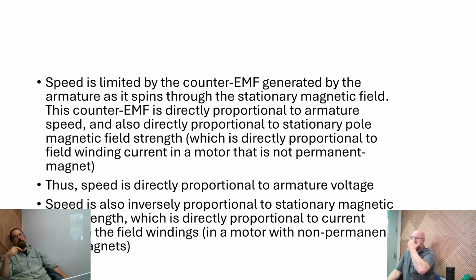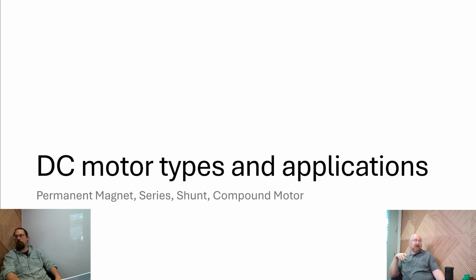But there's a limit to this. There is an upper end limit. We can't infinitely continue to supply voltage and continue to get more speed out of a motor. There's diminishing returns involved here. And also there's the other concern, which is that at extremely high speeds, if we increase the voltage too much, it will actually start arcing from the brushes. That's a material limitation that you're going to run into.